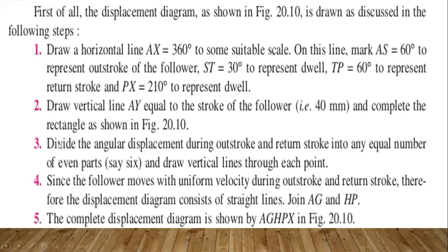Next, draw the vertical line AY, that is the stroke of the follower, which is equal to 40 mm, and complete a rectangle.